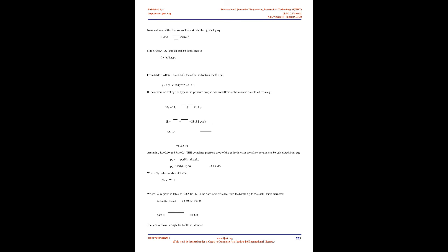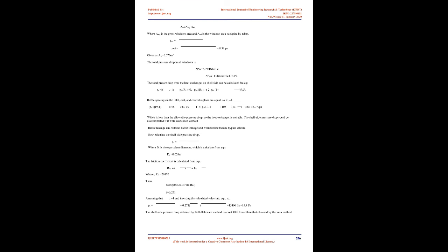7.2.7 Baffles. Baffles serve two functions. Most importantly, they support the tubes in the proper position during assembly and operation and prevent vibration of the tubes caused by flow-induced eddies, and secondly, they guide the shell side flow back and forth across the tube field, increasing the velocity and the heat transfer coefficient. Fig. 4 Shell and Tube Heat Exchanger.